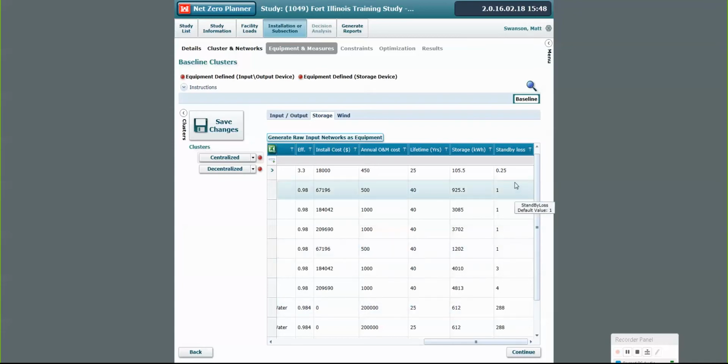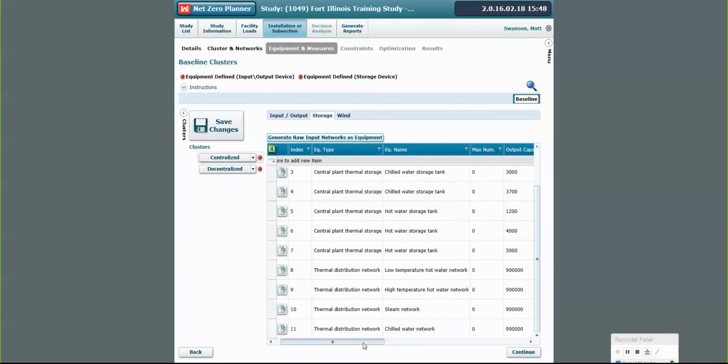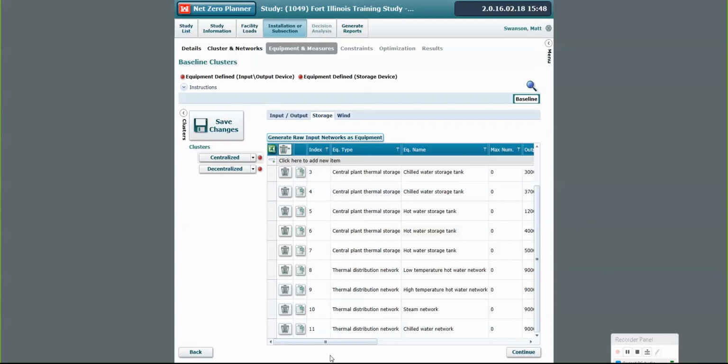And then the amount of energy that you lose over time, which is kind of a different concept. So if you've got a steam system, we talk about it a lot with steam systems, even if every building is shut off from that network, you're still going to have some loss in the network, and usually it's significant. And so that's the standby loss. We would say the amount of energy that's lost every hour in that system.